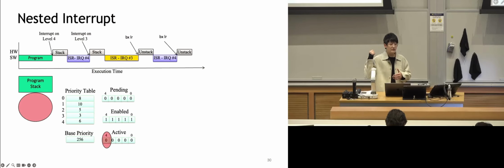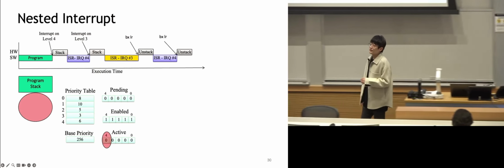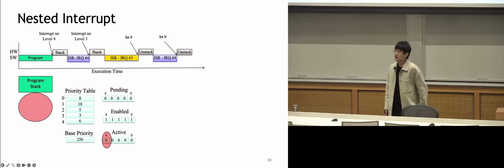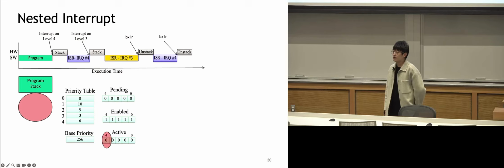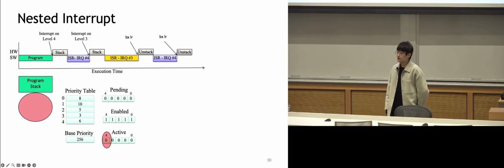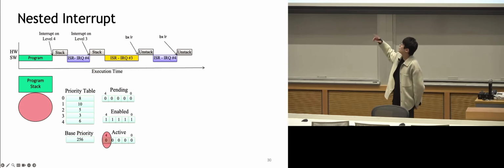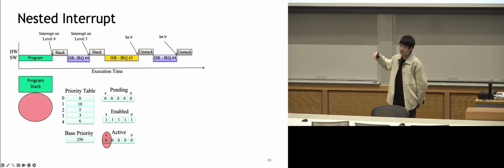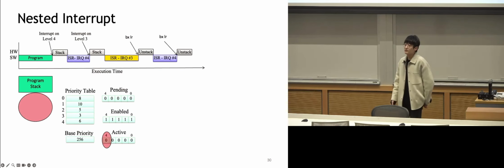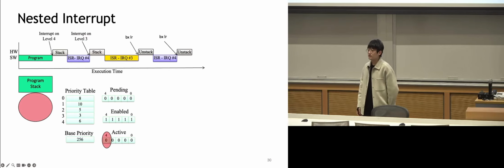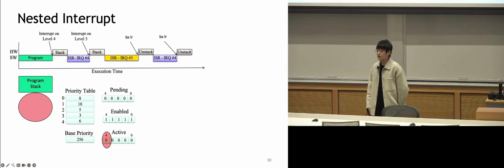Is the interrupt preemption case clear to everyone? Yeah. With the pending bit set to 0, that will be clarified. Otherwise, we are thinking that it is cleared before the ISR is executed. The pending bit goes down after the active bit goes up, which triggers the pending bit to go down. So the pending bit is cleared before the ISR executes, after the stacking.